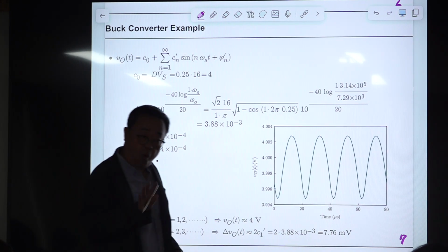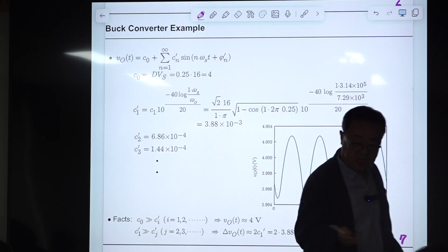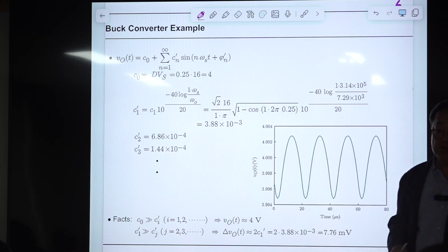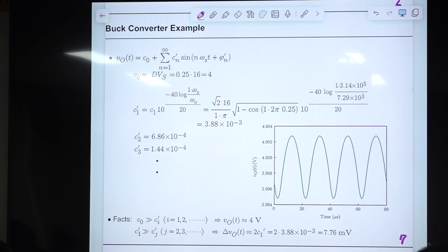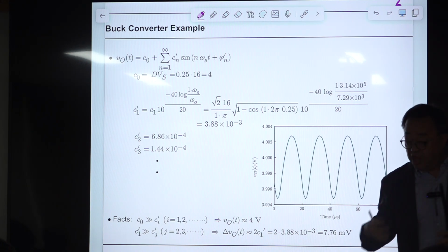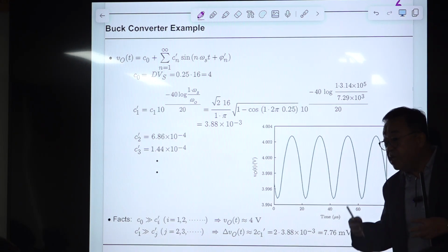Now it is called ORCAD, but they are using the same engine for the numerical integration. So they are the same thing. So the average voltage should be exactly 4, right? But in PSpice, they are using the physical model of a diode. So there is no ideal diode in PSpice, so there is some voltage drop or something.